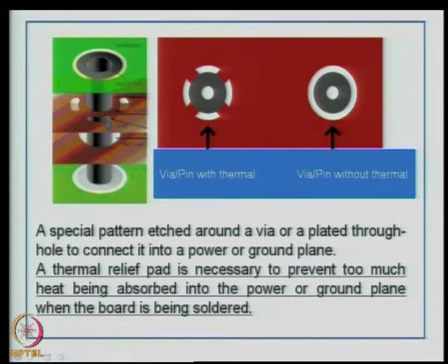And if you imagine the hole going through the third layer, here there is no copper at all touching the plated through hole, the copper is here. So, this is an anti-pad structure, and it ends in the fourth layer. So, this is a typical via containing a thermal relief pad and an anti-pad structure.